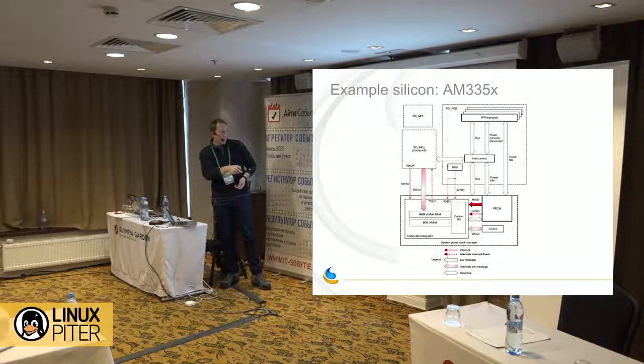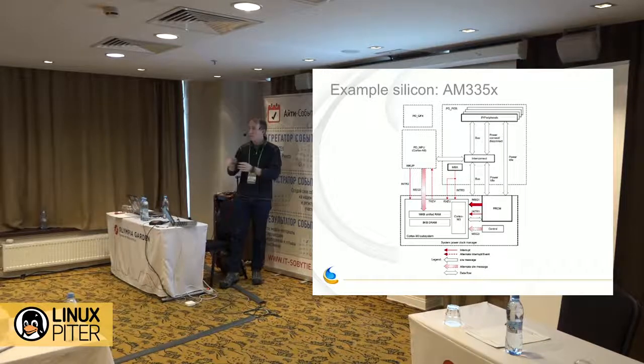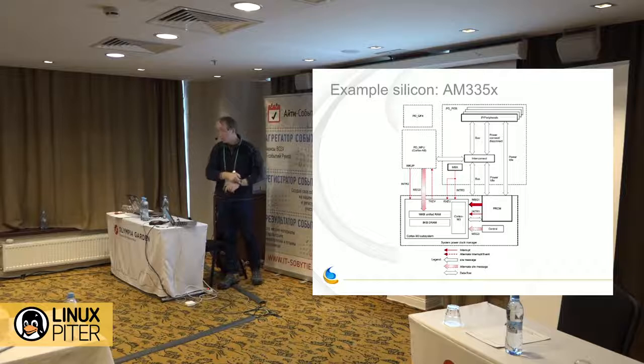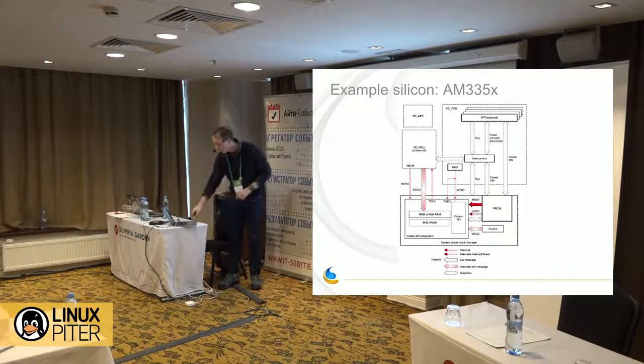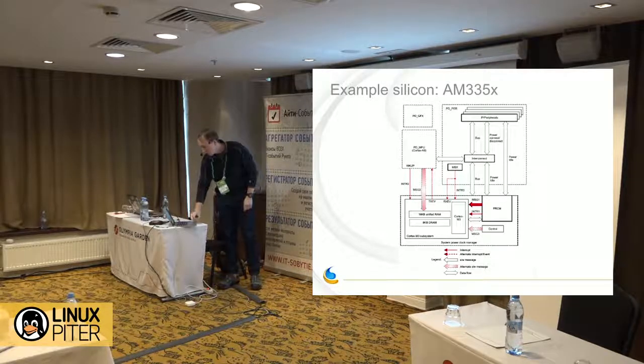Interestingly, the bottom half or third of this slide is a Cortex M3 microcontroller. Its only purpose in life is to manage all the power bits. This thing is what actually controls all the power states, both idle and active, for the whole SoC. And there's a custom message passing protocol that TI devised between Linux and the Cortex M3 microcontroller. So that's one way of doing it, sort of the firmware interface that I discussed earlier.